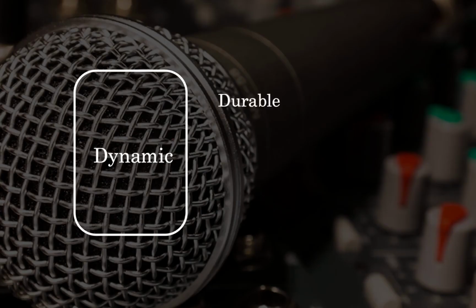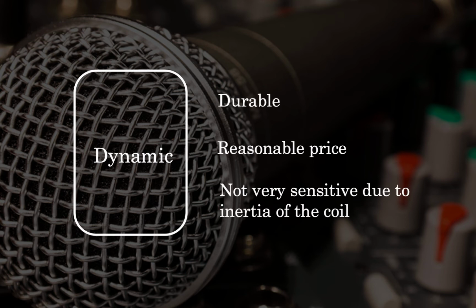Dynamic microphones are durable, that is why they are widely used in live performances. It will not break easily even if someone has dropped it on the floor. It is usually at a reasonable price, but it is not very sensitive because when the sound wave hits the diaphragm, the coil moves together with the diaphragm. Therefore, the microphone could not capture small details due to the inertia of the mic.